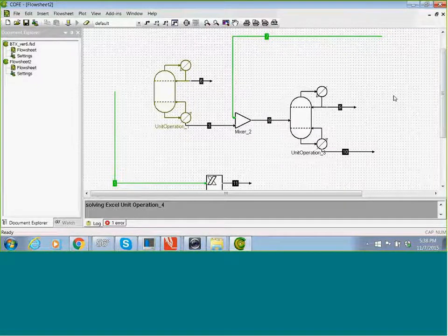It's a little more complicated than the one I just did, because it's essentially a splitter that directs components to the streams you want. All of the toluene and ortho-xylene will go into the recycle stream, and the other xylenes will go into the other stream.